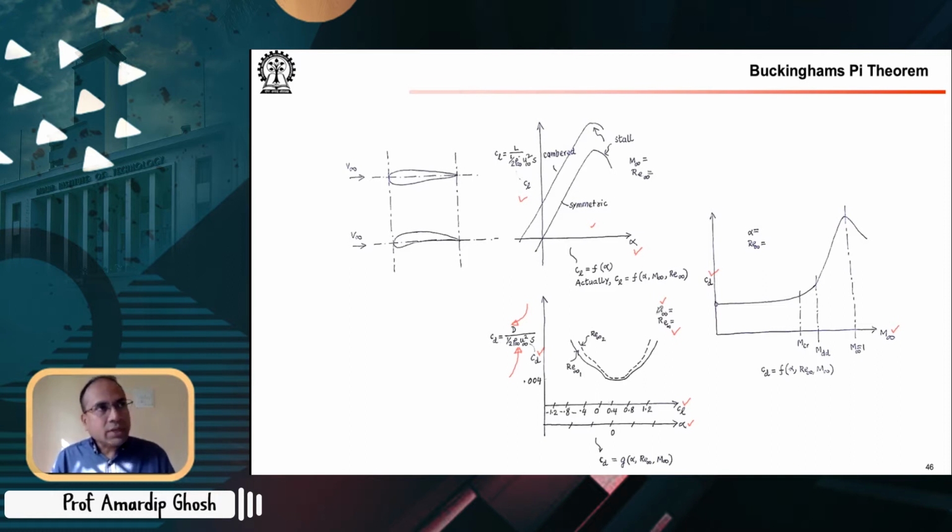So essentially, Navier-Stokes applies to flow over a small cylinder or a large aircraft, or a small wing or a large wing. Now the question is, you run an experiment on a small wing cross section. How is it relevant for a large wing exposed to a comparatively very high wind speed, etc.? So we will see that when you start with these PDEs or ODEs and you normalize and non-dimensionalize, the equation becomes one in the normalized variables, and some of these non-dimensional groups come as coefficients in front of various terms.